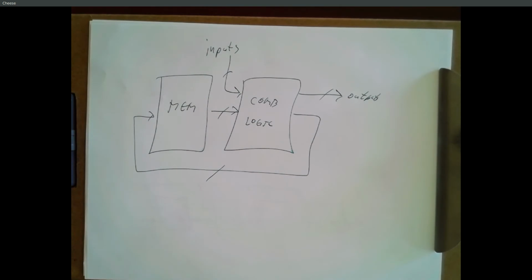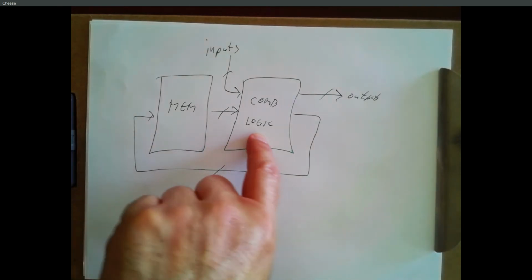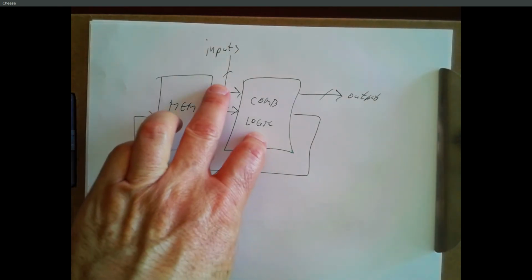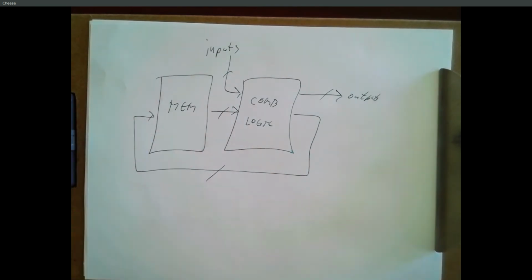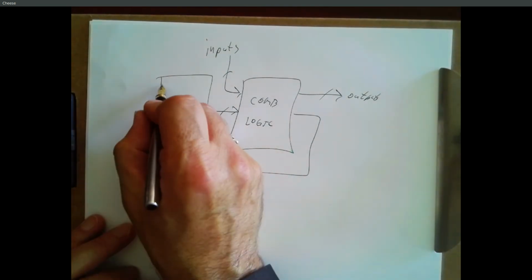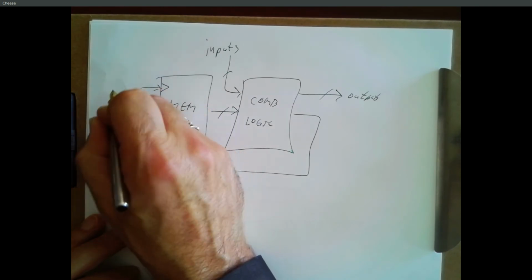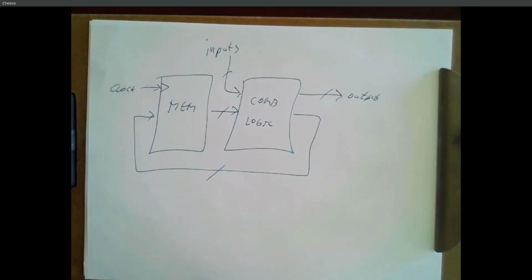That's every state machine. So flip-flops, their outputs drive combinational logic, possibly in conjunction with inputs, and that generates the inputs of the flip-flops, which will determine the next state when you have your clock tick, so there's always a clock. Okay, there's every state machine.